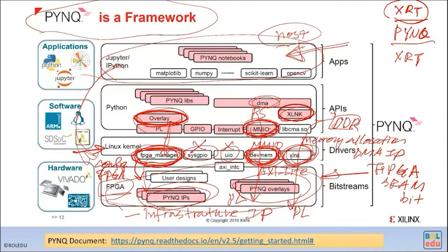Yeah, like the OS. Let's say one example, like a timer for the OS doing multitasking. It has a hardware timer. After a certain time, the timer generates a tick, it generates an interrupt, and then the OS captures it and schedules the event. So that's why I'm saying that we don't really deal with the interrupt. Do you understand?